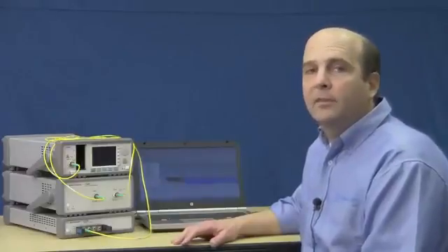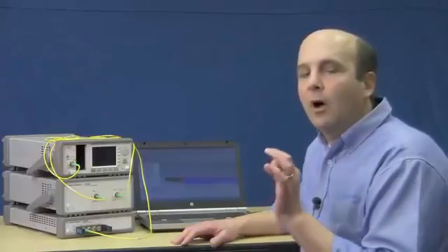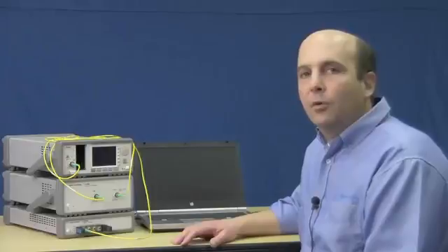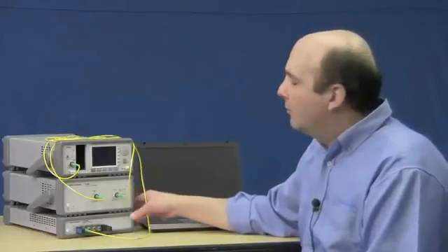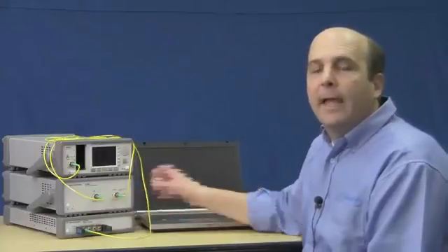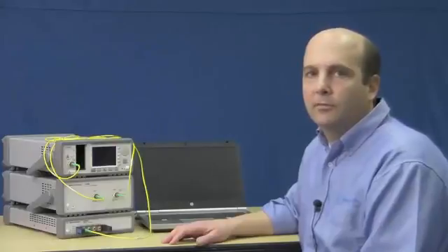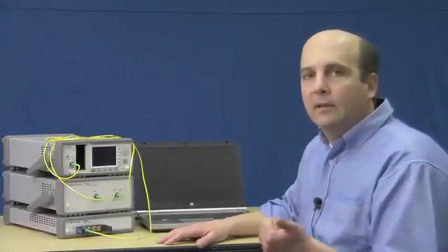And one of the main benefits of the solution for insertion loss and polarization dependent loss measurements is that it can do all of the required tasks in a single sweep. So during the course of the sweep, the polarization synthesizer quickly rotates the state of polarization while the power meter is measuring the power, and then we're able to perform the calculations once the measurements are complete using the Mueller Matrix approach.